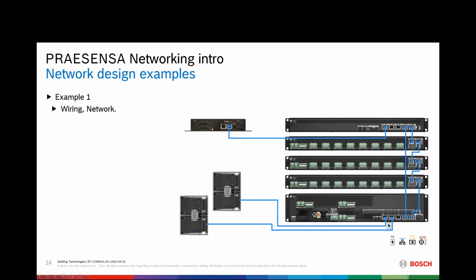But when you really need to make your physical connections later on, you will set that connection to the system controller. So it makes sense to connect it to the port of the system controller. Then you have really a one-to-one link here. And here you have this loop. So you start here, daisy chaining this loop here to the MPS, and from the MPS back to the system controller. Now we have here the two PoE ports of the MPS, which are powering the two different call stations.